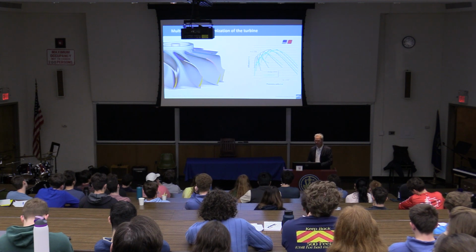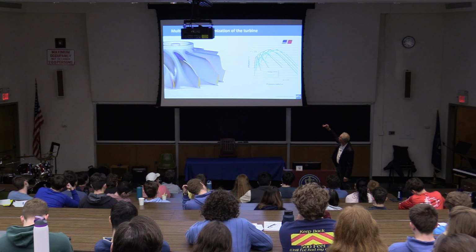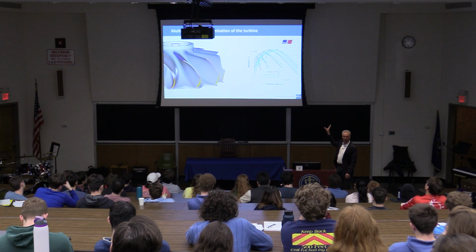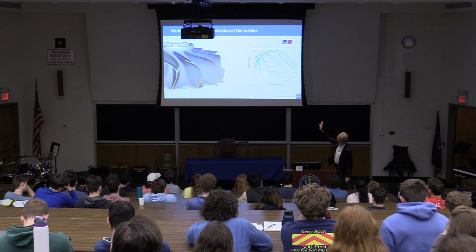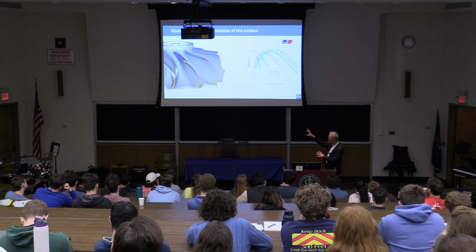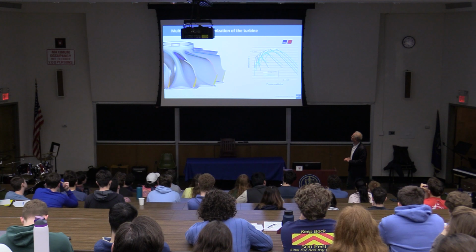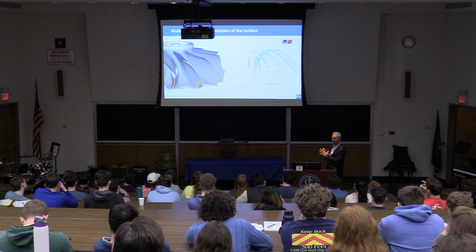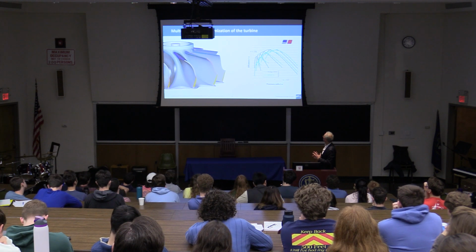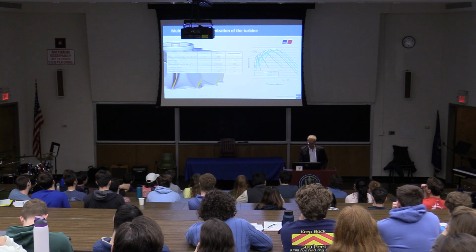In a turbocharger, you have these complicated diagrams. Don't worry about them. Basically, what I'm showing here is efficiency versus pressure. The green one was the one they started out from. The blue lines belong to the final turbocharger, which I cannot show, but it's among that family of turbochargers. So you see that we have an improvement, indeed, of about 1%, as they hoped, and actually even, so to say, covered the operating range a little better.